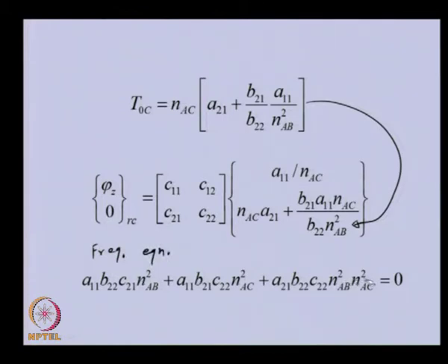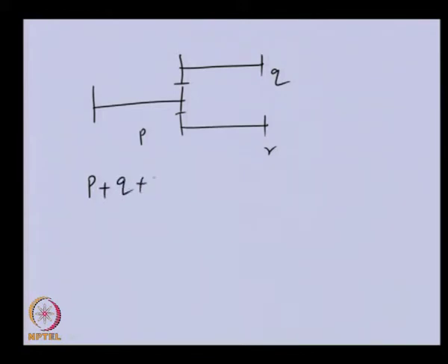and in this particular case we will be having many natural frequencies, and how many, let us see. In branch A we had P number of discs, branch B we had Q number of discs, branch C we had R number of discs. So, total degrees of freedom we expect this much, but the angular displacement of branch B at this point is related with this by the gear ratio.